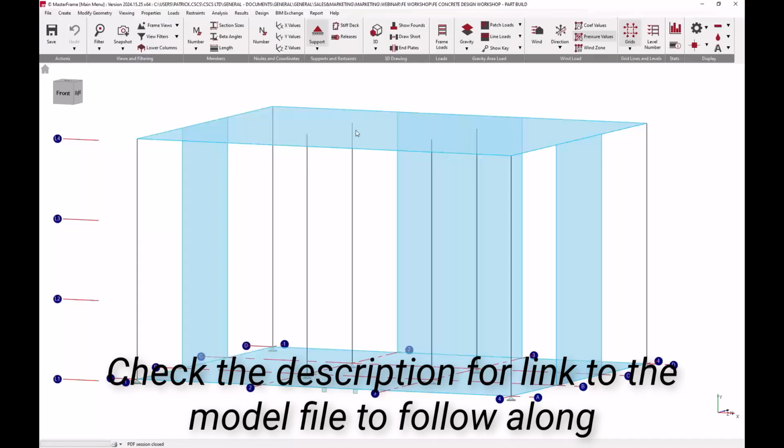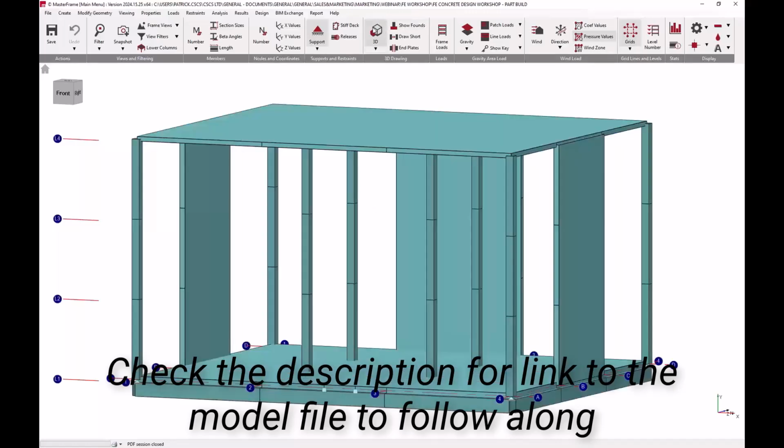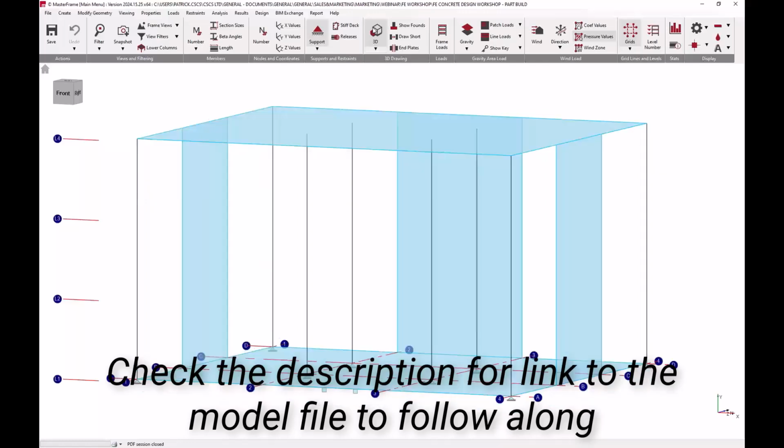So we've got the frame outline, including the nodal supports, all our columns, properties assigned to the columns. We've got 2 slabs already created, so roof slab and a ground floor slab. We've got 3 out of the 4 shear walls included as well, so we can build up 3 FE surfaces there. So we've got our grid lines and our levels defined as well, and then we should have our wind loads and load combinations already applied.